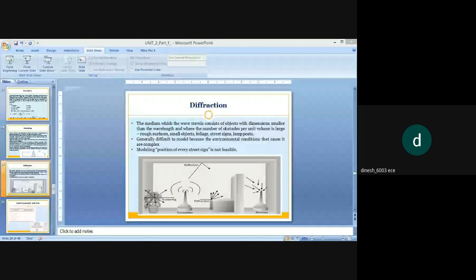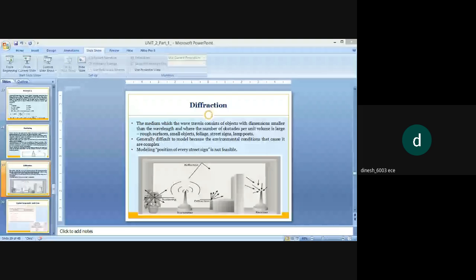In free space, the path loss exponent n value should be 2, and in an urban area it should be around 2.7 to 3.5. For shadowed urban cellular radio, it should be 3 to 5. In a building with line of sight, it should be around 1.6 to 1.8. In an obstructed building, the path loss exponent should be from 4 to 6. In obstructed factories, it should be around 2 to 3.